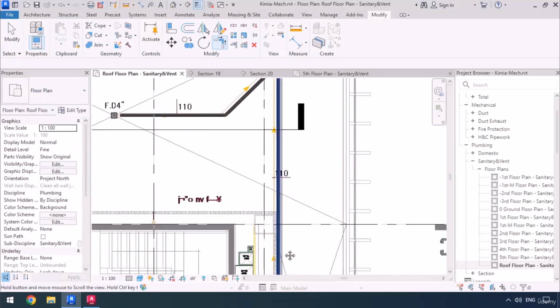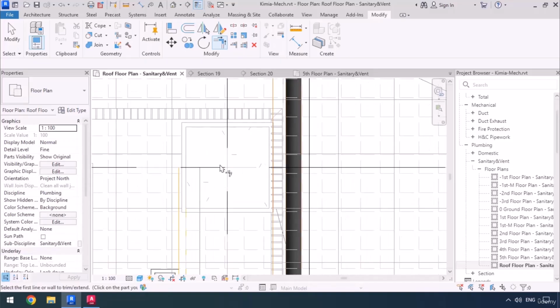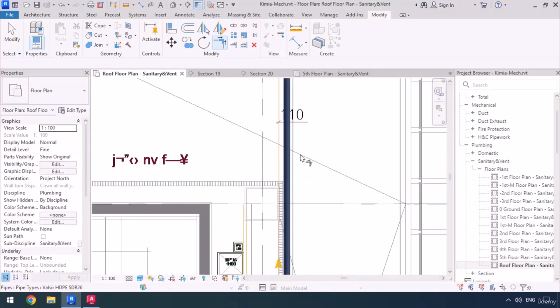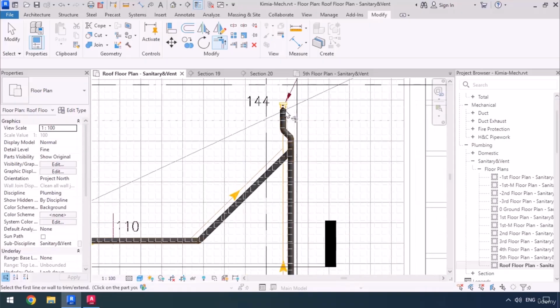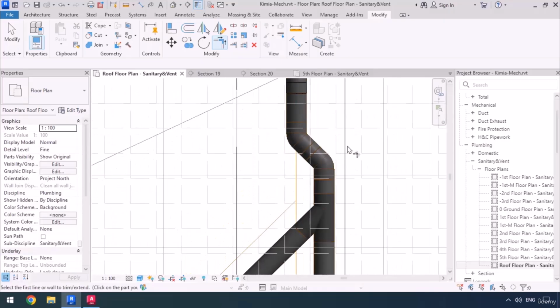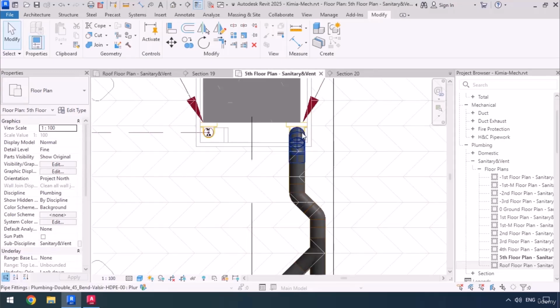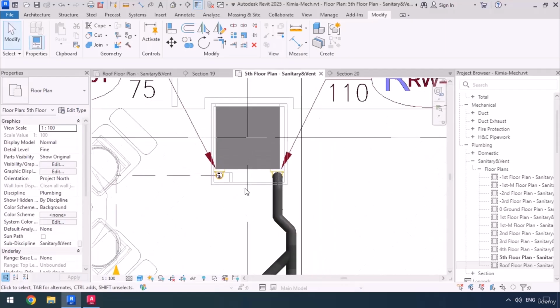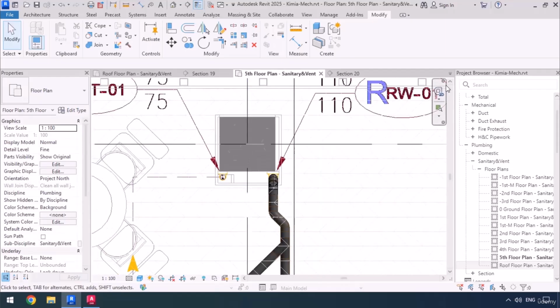Okay, so over here we needed to draw our pipe a little farther to the right to avoid its interference with the beam or column. And then up here, to make sure that we place the riser exactly as it is on the plan, we had to change the direction of this pipe and then connect it to the riser by using two 45-degree elbows. So now the path of the riser in the levels 4 and 3 have been fixed, which means that the vertical riser pipe is now within the column cover.